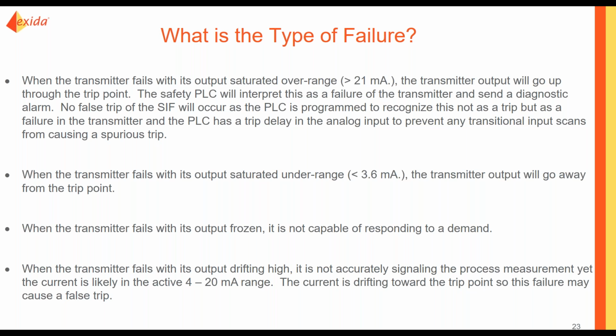So these failures do not meet the definition of fail-safe. However, the transmitter is not capable of responding to the demand until the repair is made. So the failure class would have to be dangerous detected.